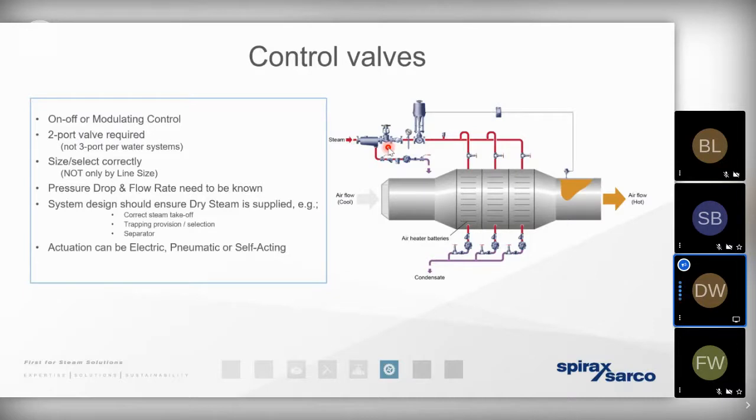Common problems that we often see with control valves are these conditioning ancillaries are missed off, at which point, if we're exposing the control valve to wet steam, we will get that erosion. It means that we're not controlling the steam efficiently. That can impact the process, and it can have a financial inefficiency, and you could forever be replacing the internals of that control valve. We also often encounter control valves that are oversized, and when that happens, then the control valve internals will be operating far, far closer together, and that's only going to cause a greater effect of that erosion that we were speaking about.